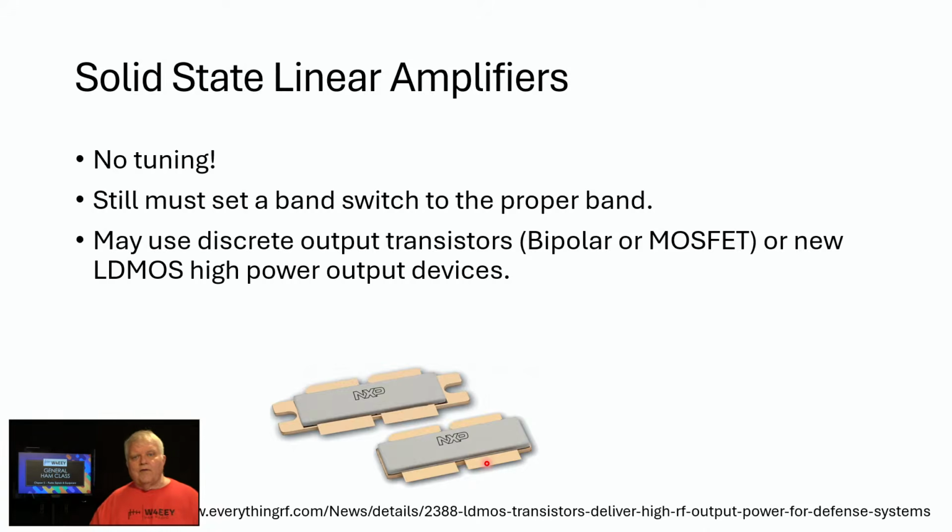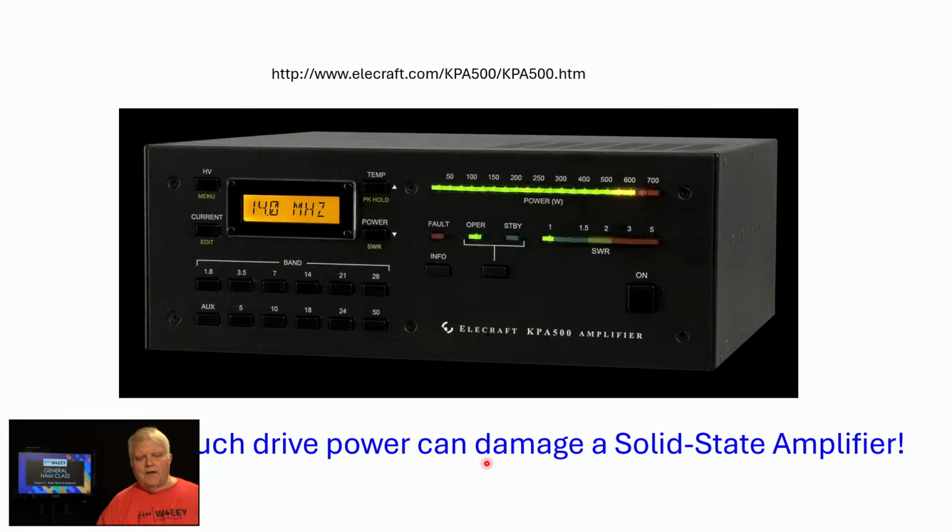Solid-state amplifiers, like the ones that I have, Elecraft KPA500 or my RF Kit, use solid-state devices, in one case LDMOS devices. For those, you have to change the band that you're operating on. That can be done automatically sometimes with computer-aided transceiver control.